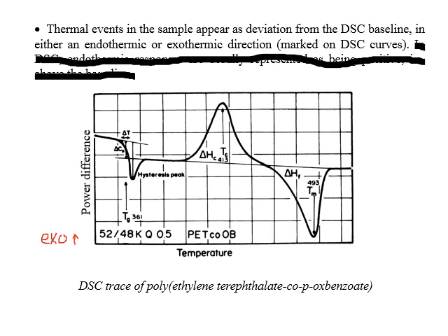But so we start with some kind of a hysteresis peak. The initial drop or use of energy is the Tg temperature of the PET, followed by hysteresis from that Tg. And then the first exotherm, so that's an exotherm. That's actually the temperature of crystallization right there, the peak of that exotherm. So exothermic events are generally crystallization events, where you're actually putting off heat to form that crystal structure.